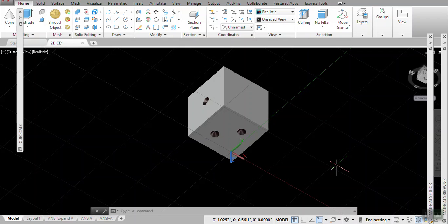UCS face enables you to do that. We drew the lines intersecting geometrically correct locations of each cone. We created those cones so that we can subtract them. We subtracted those cones so that we can change the colors to black marks, okay, on the dice. And then finally, we erase the lines that we drew at the end, okay? This is what we did.